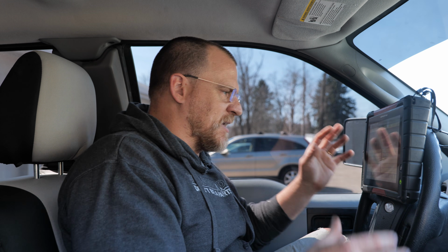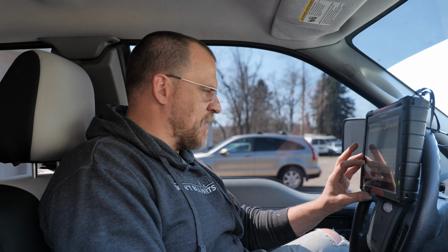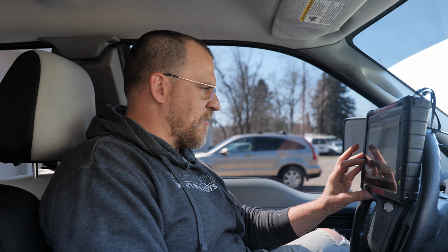The MAP and baro out of range code can be just from low power, poor idling conditions, maybe starving for fuel. You can certainly set a MAP code. That's not unprecedented. So all of this could be tied together. I didn't anticipate this being as simple as, hey, we just maybe have a bad pump.